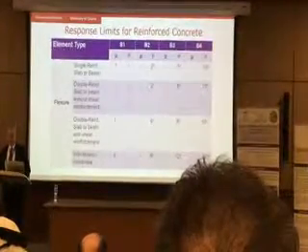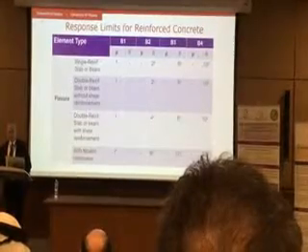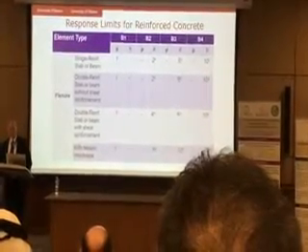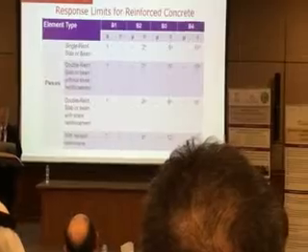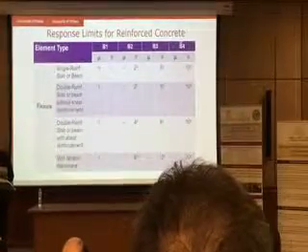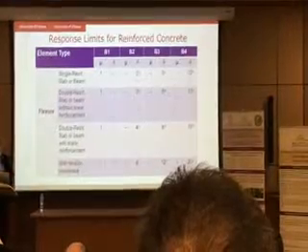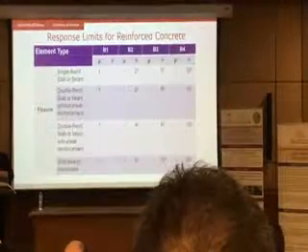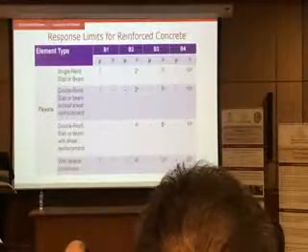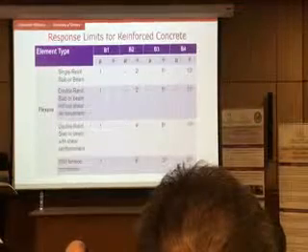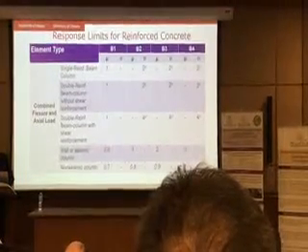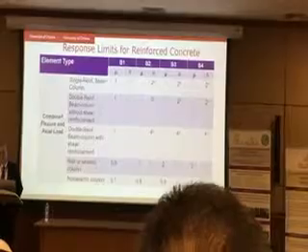So if I'm going to design a building for a very low level of protection, that means I'm interested in B4, so my column has to have support rotation of 10 degrees. If it exceeds 10 degrees, then it will have to be strengthened. And similarly, the other one was for beams and slabs.